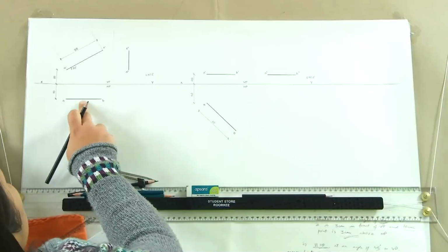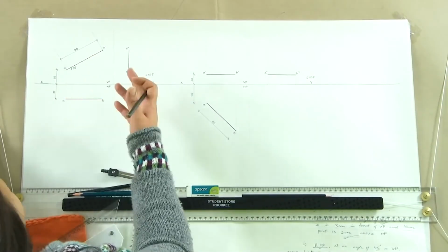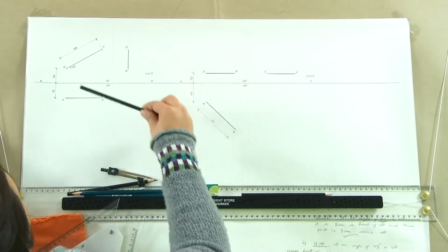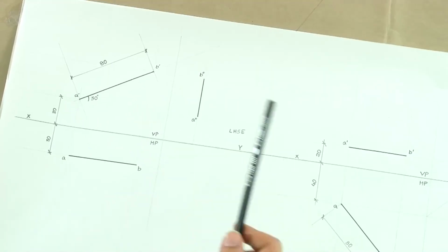Always the darkest lines will be the ones which are the projections of the actual object. The next ones come the reference line, then the dimension lines, and the last and the thinnest of them all are these projection lines, which are just the guidelines and nothing else. And in case you are drawing guidelines for writing the text, then those guidelines are also as thin as projection lines or even thinner than them. They should not be seen, they are just to guide us.